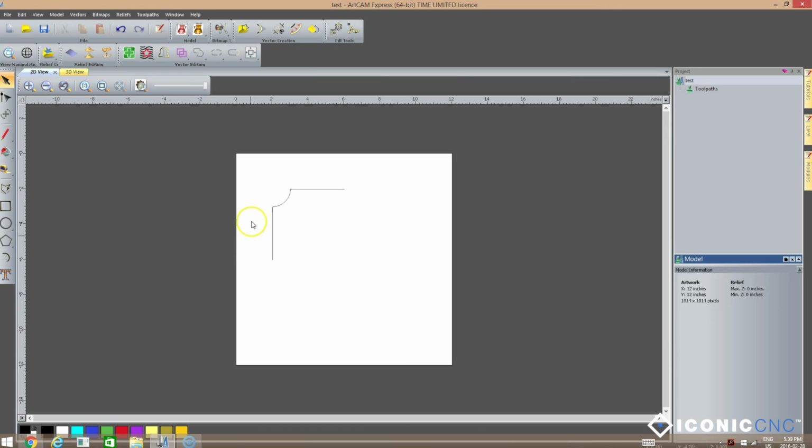So now what I'm going to do is I'm going to drag my mouse over all three of these vectors because they're all independent. Now you'll notice when I do that drag function, I have to drag my mouse. I'm pushing my left mouse button down and I'm dragging, creating this bounding box around all three vectors. If I don't have them completely inside the bounding box, watch what happens. You see, I only selected these two because the bounding box didn't completely envelop all three. Once I have all three inside, now it has all three selected.